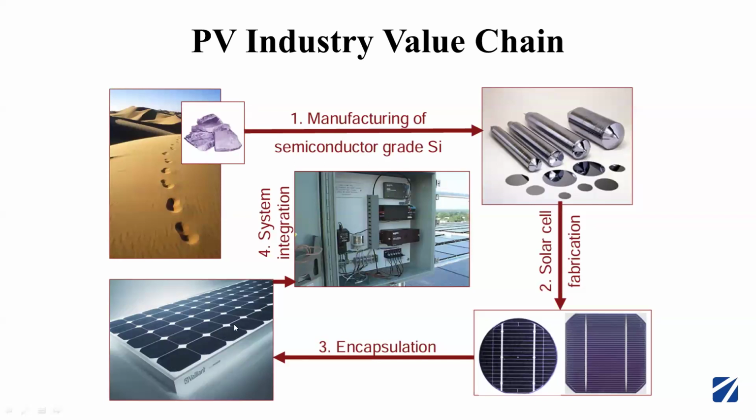All the solar cells are connected in series. So many, about 60 or 72 cells, are connected in series. And when they are connected, first we have a back sheet, and then we have an EVA sheet, that is an encapsulant, and then we place the modules, and then again EVA upon those modules, and then a glass cover, and then they are framed. So this is how